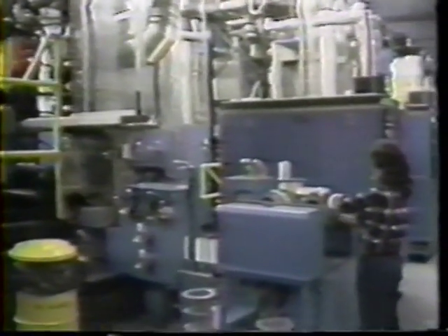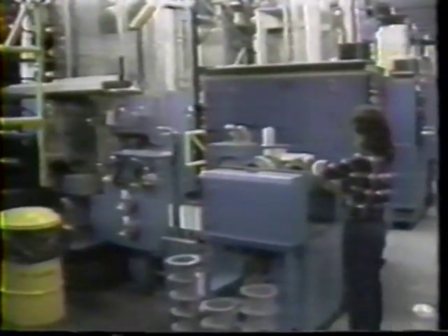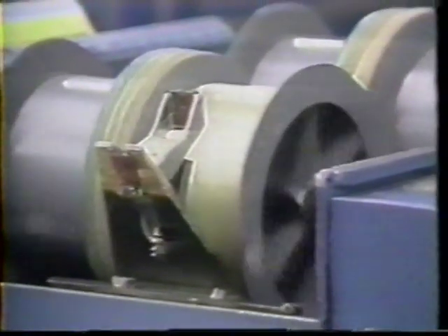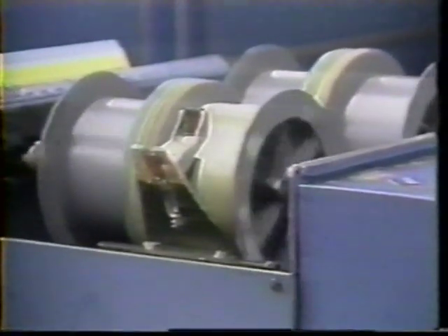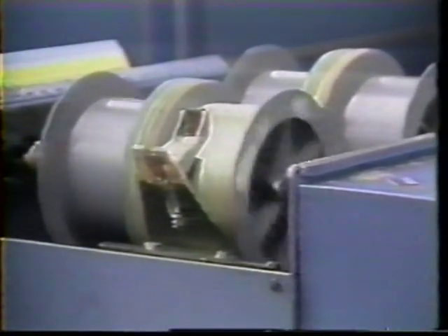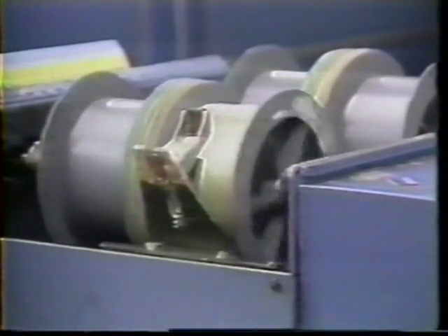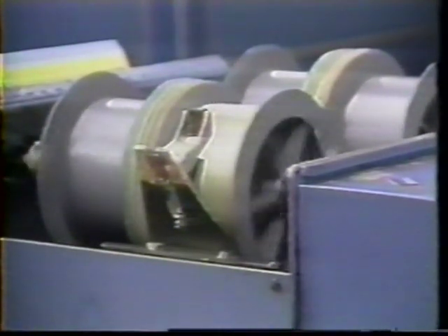Finally, the freshly coated fiber passes over a drawing capstan, which has been controlling the entire pulling process, and is loosely wound onto lightweight plastic take-up spools. One preform has yielded over 10 kilometers of light guide fiber. The fiber's cross-section, although considerably smaller, faithfully duplicates the layered structure of the original preform.